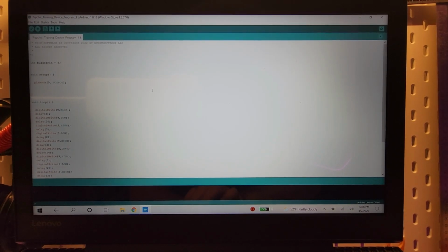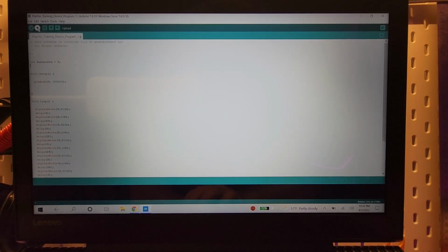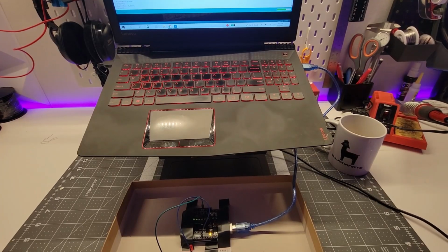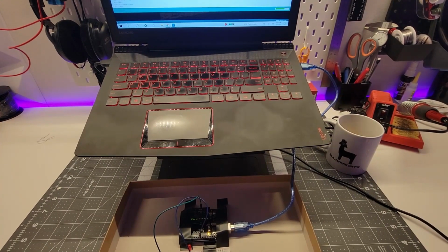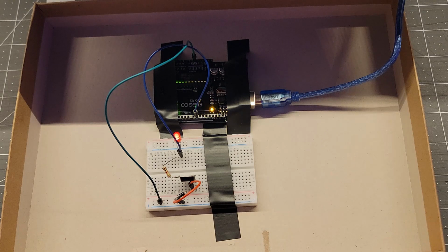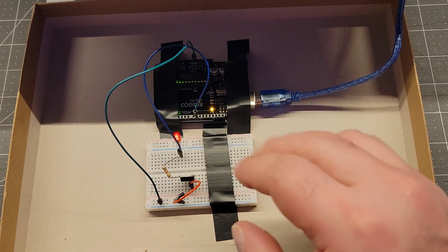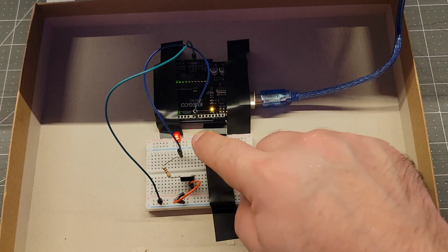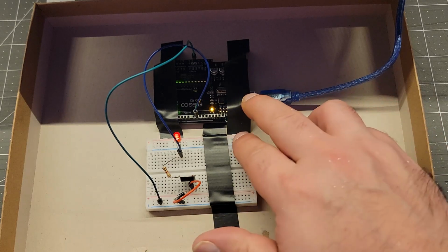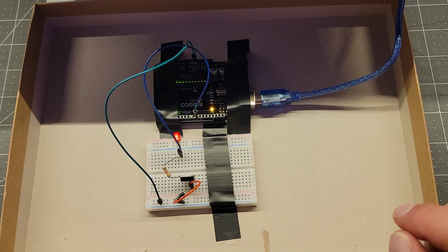Now, all you need to do to flash the board is click on Upload, this little forward-facing arrow. Click that, and down here in the right side, it's going to show you your progress. You'll see that when that bar finishes up, your device will flash. And there you go. You notice that the light just went out and flickered and flashed back on the board, and now your LED light is flickering, and that means the program is uploaded to the board and it's being powered by the USB, and the circuit is working correctly, and this is exactly what you want to start with.